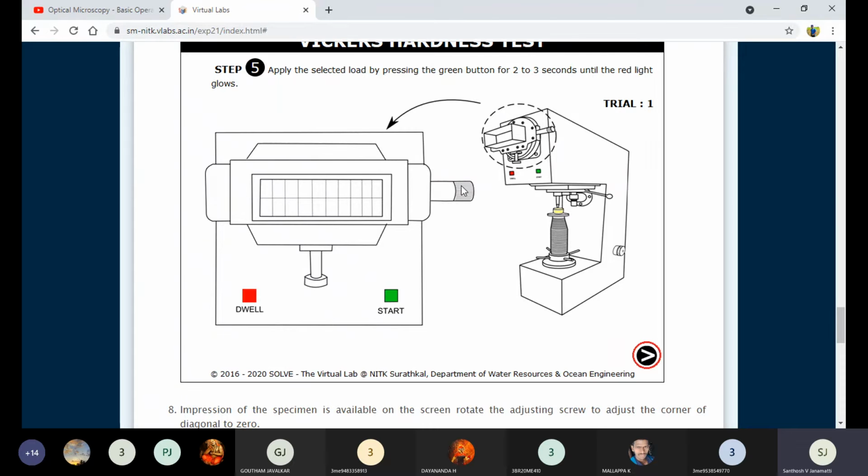Now with the help of a screw gauge, or the micrometer, we can adjust the image properly. That will cover a number of lines. These are the millimeter lines. You have to set it properly, making sure that both ends of the image properly touch the lines.